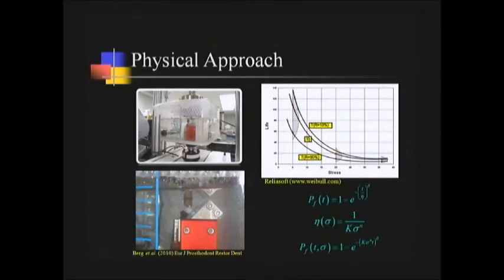And so in here we are actually making a ceramic crown and testing it, not a disc-shaped or bar-shaped specimen. And what we will do is we will load that with a higher bite force than we see in the clinical case and measure the distribution of lifetimes until failure. And then we will have another group of specimens that we load at a lower bite force, however, still higher than we see in the clinical case. And this is what we mean when we say accelerated lifetime testing.